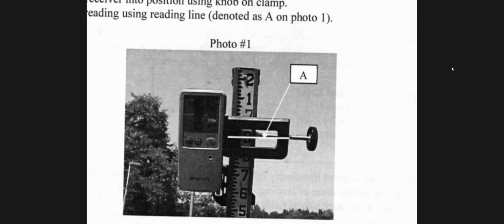The receiver will beep. And if you're too high, it's a faster beep. It goes like beep, beep, beep, beep, beep. And then as you get down toward the point where it's level and reading the beam exactly where it should be, you'll get a solid tone.